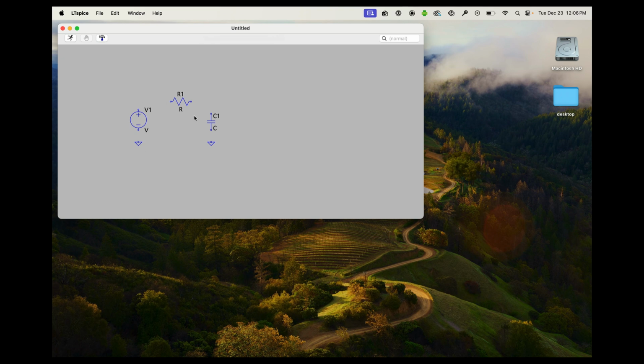So let's wire these together. We need to get our wiring tool. Again, this is in draft, and we'll say wires, or F3. And now you can see we have a crosshatch. So every one of these has a little terminal to connect the wires. So if I click, and then I can click again, and then click again. So now those are wired together. And you could keep going, click, click. In fact, we'll just do that one.